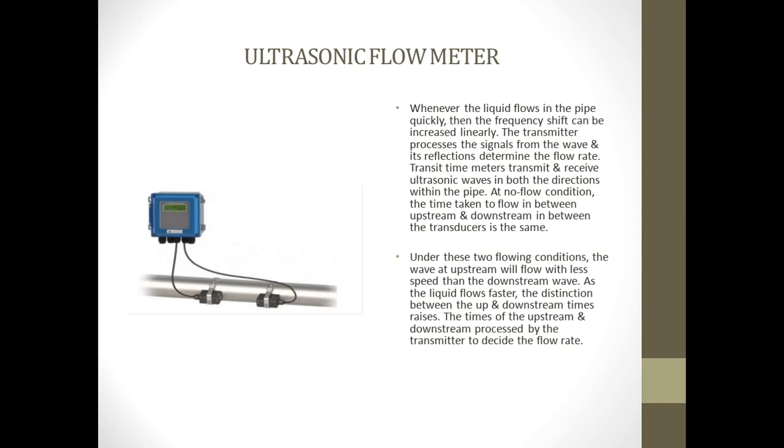The receiver crystal is exposed to these pressure fluctuations and responds by vibrating. The vibration motion produces an electric signal in proportion, according to the action of a piezoelectric displacement transducer. The transmitter emits an ultrasonic pulse which is received at the receiver at a delta t time later.